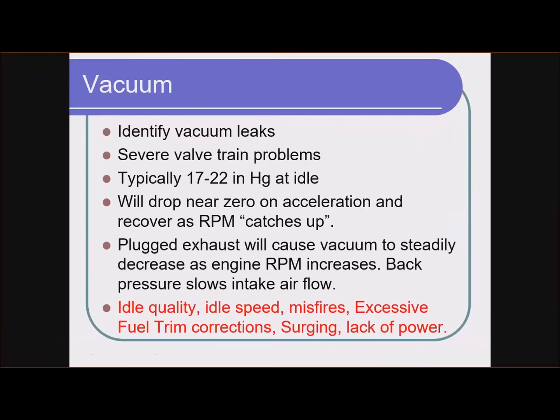We can verify the vacuum test results with this exhaust back pressure test. And what we saw in that is that exhaust back pressure on a normal engine is very, very low. It was less than a pound, really, under almost all conditions. We got it to go up a few pounds when we literally stuffed rags in the exhaust pipe. So exhaust back pressure is supposed to be pretty low.